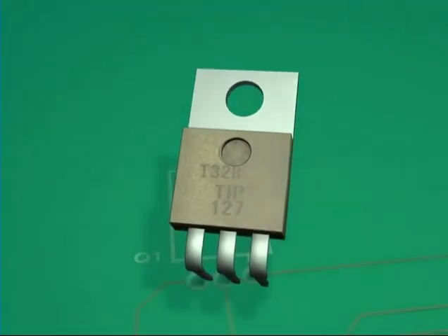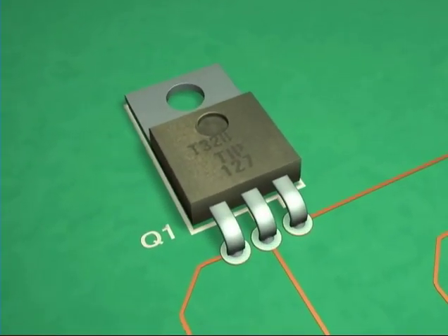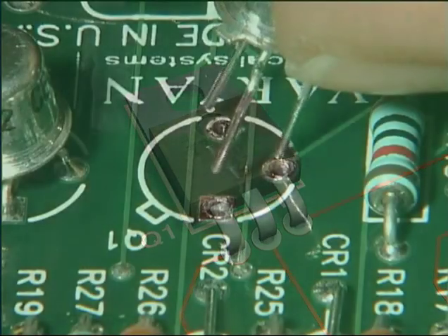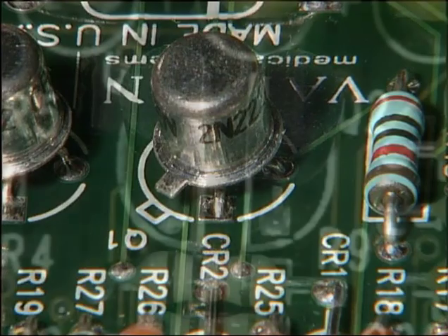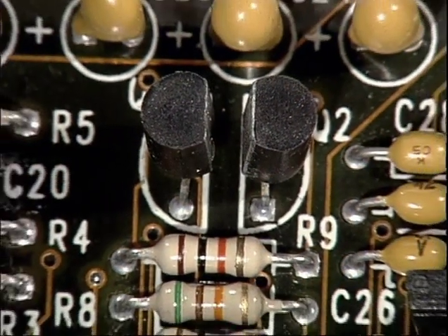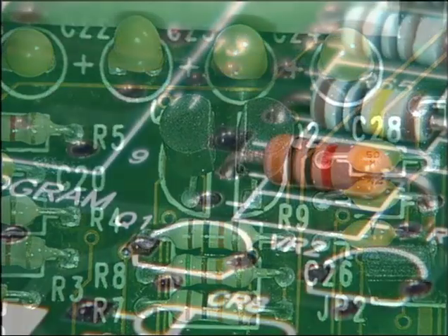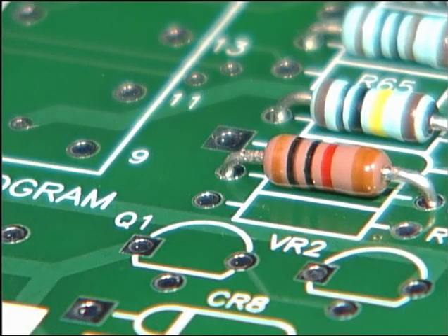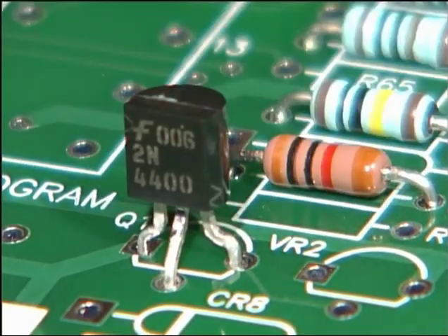Orientation may be accomplished by matching marked pin numbers on the transistor to pin numbers on the drawing or circuit board, by locating pin 1 to the right of the tab on a transistor can, or by matching the component shape with the outline on the circuit board or assembly drawing. Sometimes the pattern of holes on the circuit board indicates there is only one way to install the transistor.